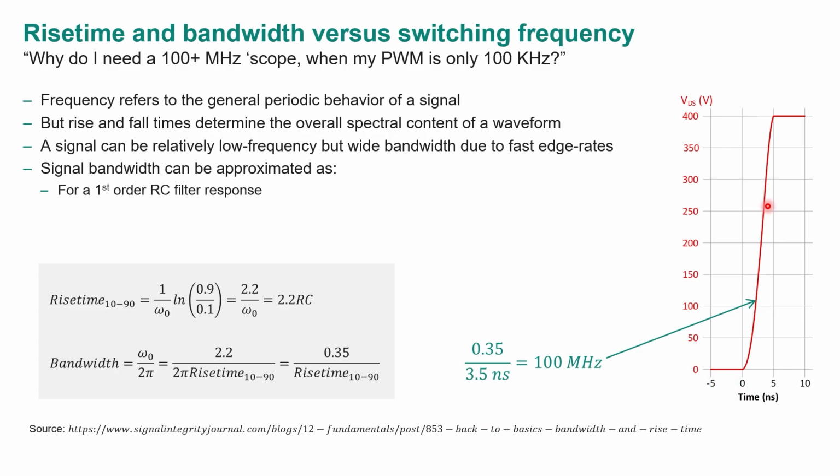Now, if I'm measuring this signal on a 100 megahertz scope, I have to ask the question, is it the scope that's limiting my rise time? Is that what I'm seeing as the limit of the scope? Maybe it's even faster on my real circuit. Really, I believe you need 500 megahertz, and even a gigahertz for very fast switching GaN devices.